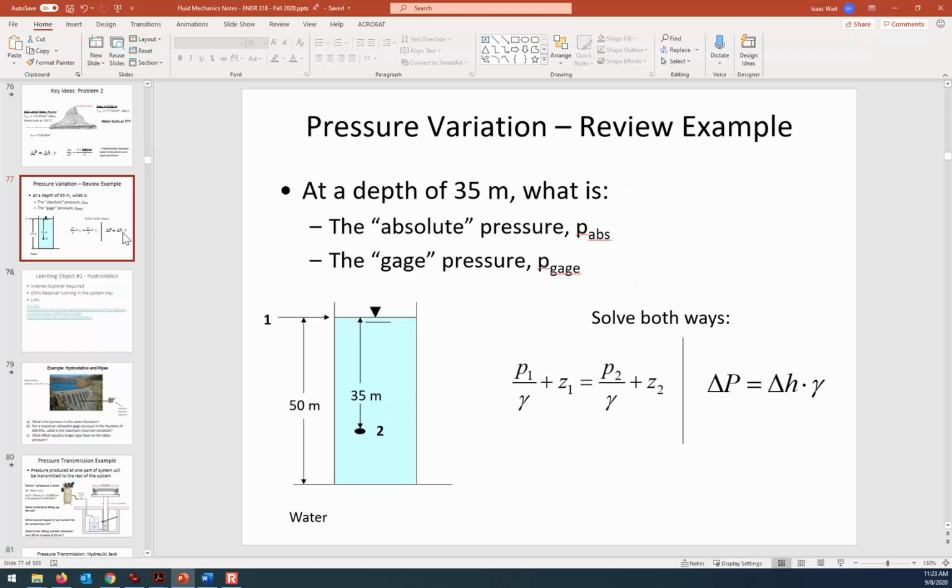If water is flowing through a river, then the hydrostatic equation isn't going to exactly describe the pressure elevation profile. If water is flowing through a pipe, then there's going to be huge variation between what the hydrostatic equation predicts and the actual pressure.